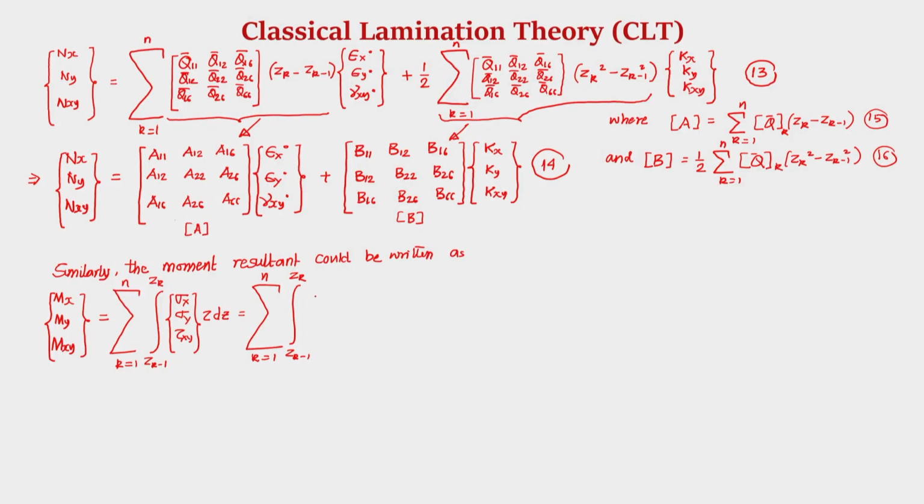So, here we write this as Q bar for the kth layer and multiplied by the strain, multiplied by the corresponding strain.